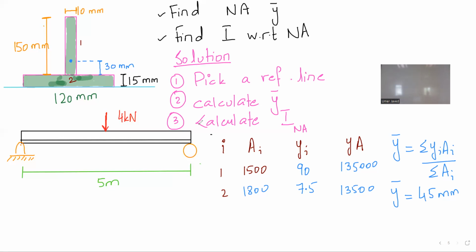So the neutral axis is a little below the middle of the vertical plate, because this whole object is one entity and the centroid that you are calculating is for this whole entity. That's why the centroid has shifted a little, because you have this big ginormous mass sitting here. If this was not here, your centroid of this rectangle was nice and clean here.